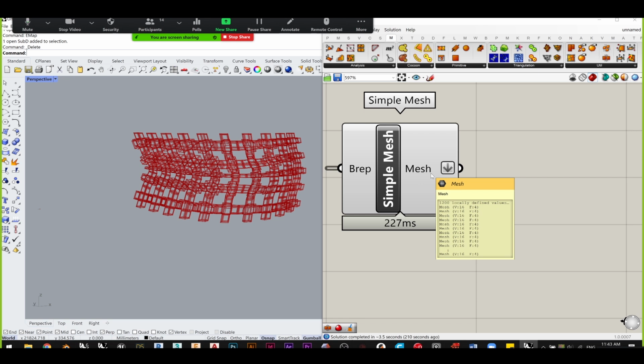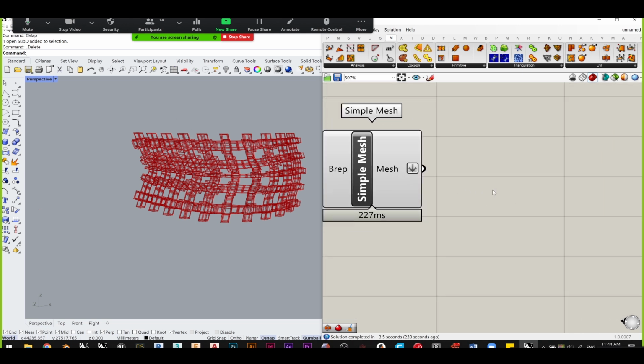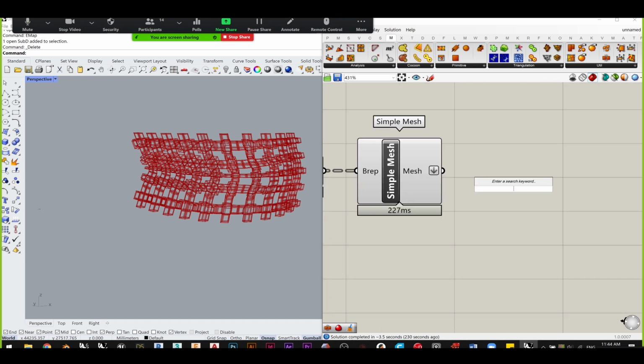The reason why I flattened this is because if meshes weren't in one list, if they were in separate branches and I tried to join them up, it wouldn't work because they wouldn't see each other, so to say. In this case, I forced them to be in one list with Flatten, and now they are ready to be joined up. And I'll join them by using the same command as I did before, Combine and Clean.